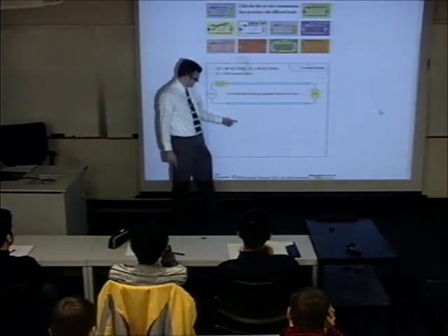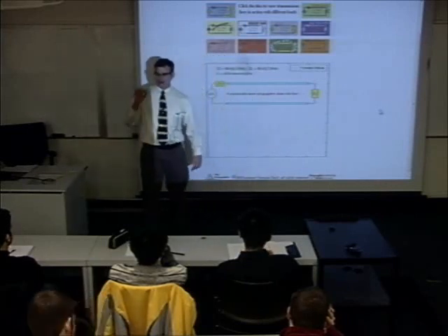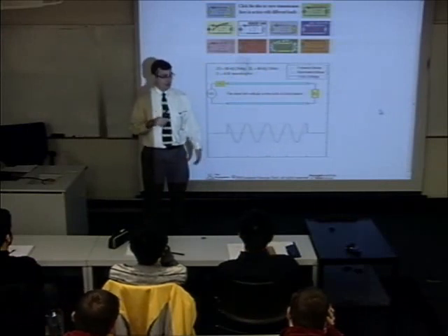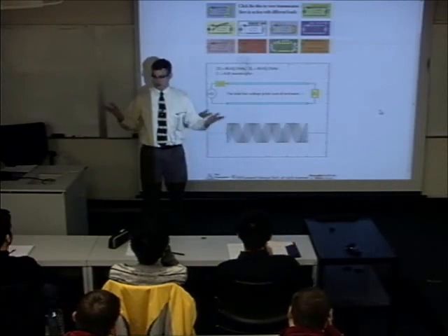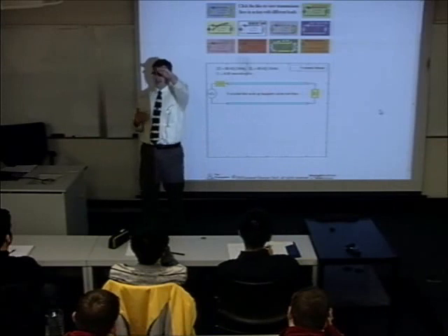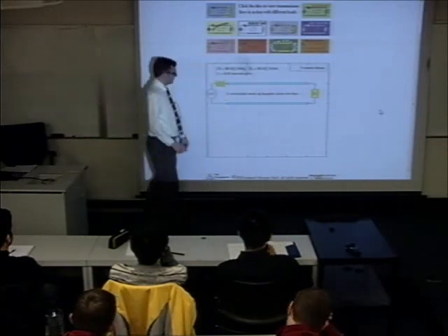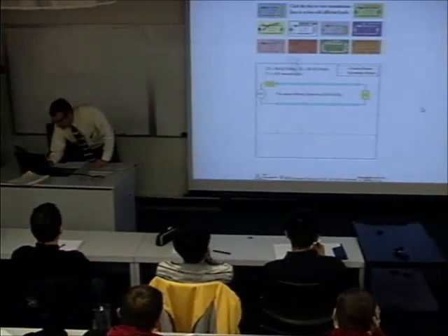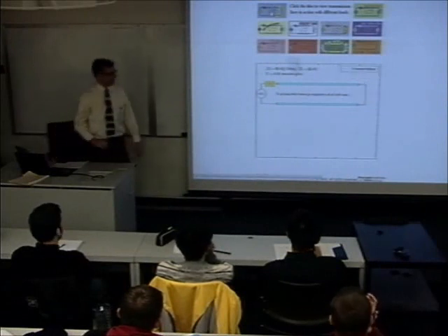Oh, look at that. That's a nice thing about a matched line. The amplitude is always the same no matter where you measure on the line. The phase is different, but the amplitude is always the same. And that's why we say that the VSWR is 1, or 0 dB, the minimum possible value. Vmax is equal to Vmin, no matter where you measure. The trivial case.